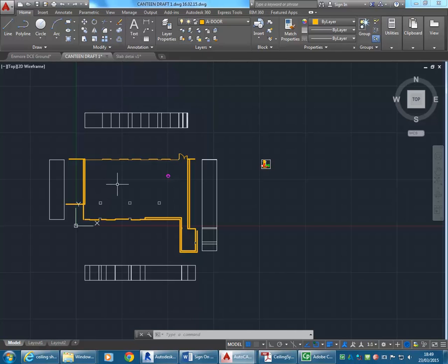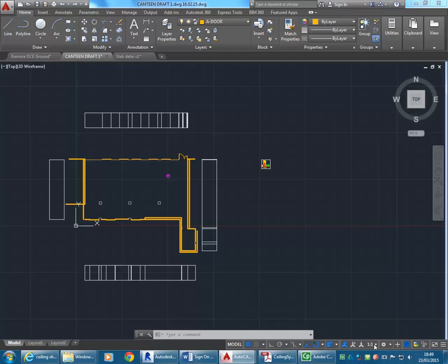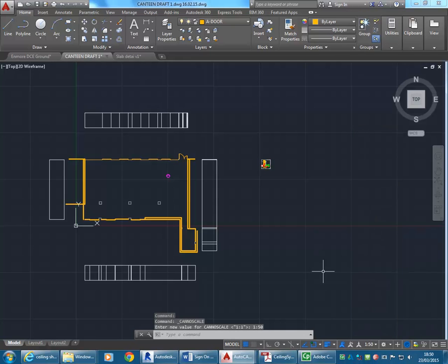So that's not the only thing. Before I do some text, I then need to have an idea what scale this text is going to be used with before I've even made a sheet. And that's what this little button here does. People think that by choosing a scale here, they're setting a scale to the whole project or to the whole drawing. It's not doing that at all. It's just setting a scale for your annotation. So text and these other things I'm going to be showing you. So maybe 1 to 50, you need to produce your drawings 1 to 50. So I'll choose that scale.